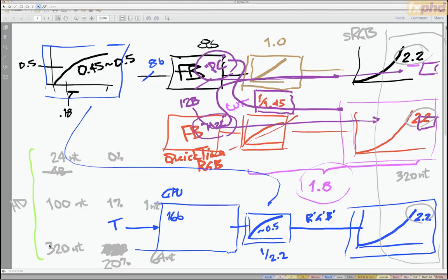And the way we do it is we mess around with the gamma number at the back end as a function of the display and viewing characteristics. And what we do basically is we choose gamma 2.2 in the bright situation, 2.4 in the dim HD situation, and 2.6 in the totally dark cinema situation.